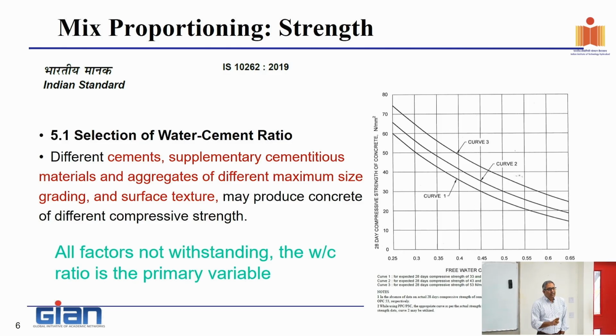But please remember that if I start going up this curve in the hope of achieving more strength, I'm doing two things. I'm increasing the cement content, and at the same time I'm making my paste thicker, more viscous, yield stress increases, and all the wonderful things that happen because of that. So now let's explore what happens when we start tinkering with these and what other levers do I have.